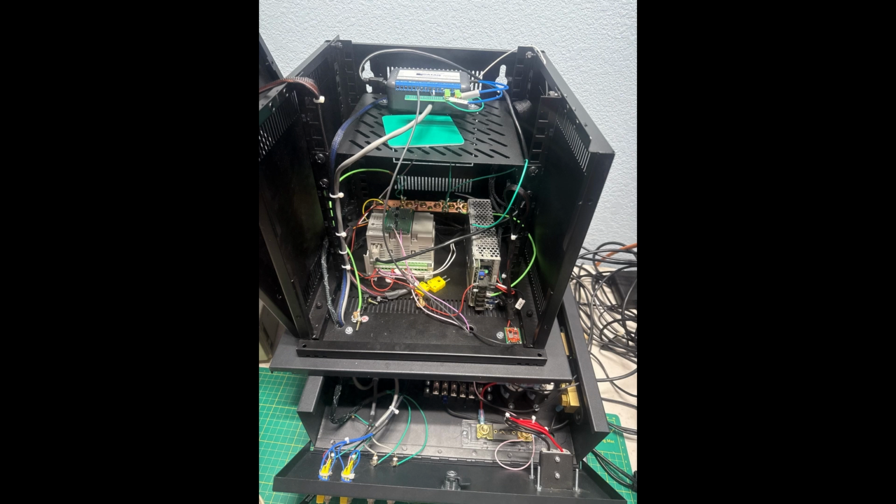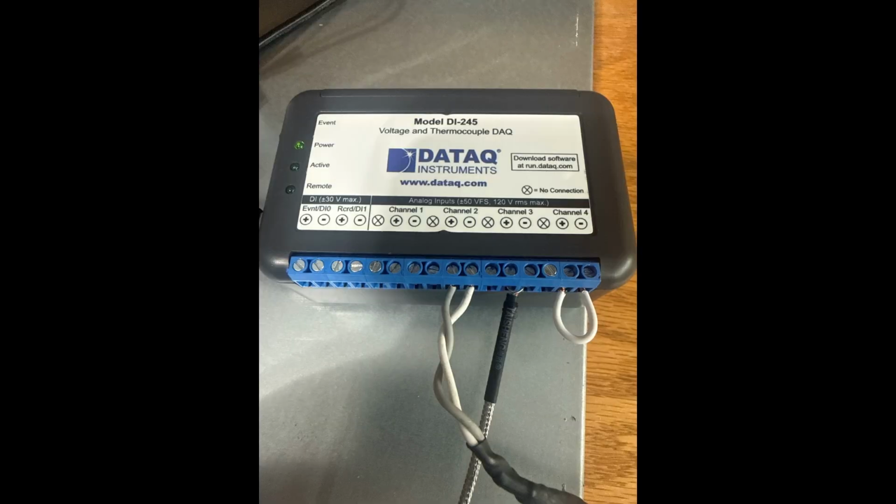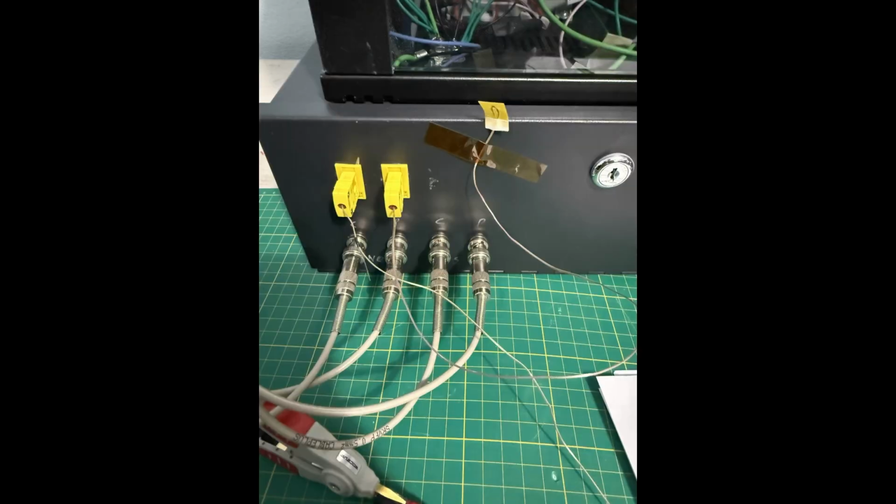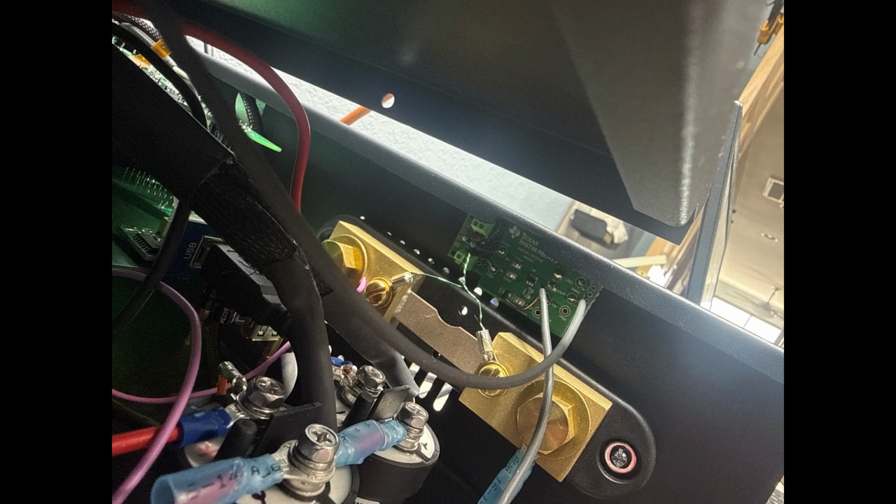We can swap out components like the power supply and load component hardware for much tighter tolerances as well as higher voltage and current ranges. The system includes a DAQ, which is a high-speed data acquisition device. That's where all of our measurements come from. It tracks the voltage, monitors two thermocouples, and most critically, measures current. Current is measured through a shunt and several layers of custom designed filters.